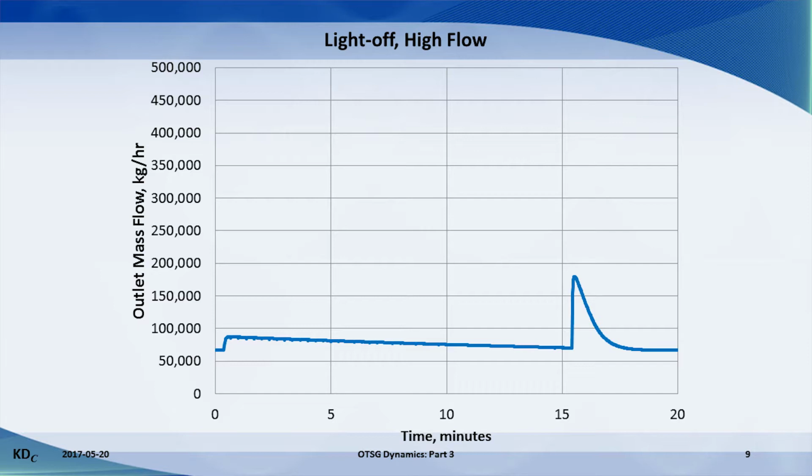The startup control valve will have a much better chance of keeping the pressure on set point. Notice that the OTSG reaches steady state in exactly the same time as compared with light-off at the lower flow rate.